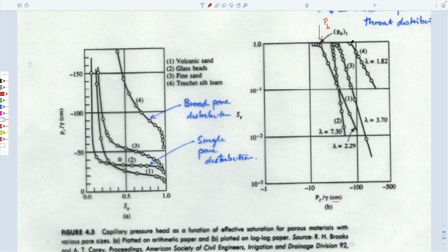So a larger bubbling pressure would, on this, relate to this. Right? We talked about this before. So number 4 would be here. It's the largest of these bubbling pressures. And so as you go to the right here, you go progressively up in this scale. And physically, what that would mean is a progressively smaller and smaller pore throat diameter as you go up in this direction. It would say something about it.